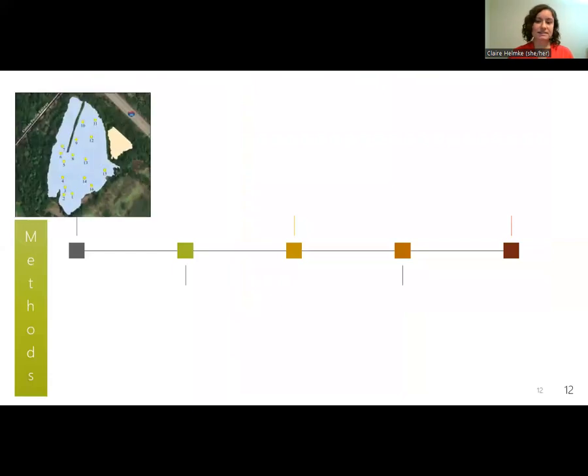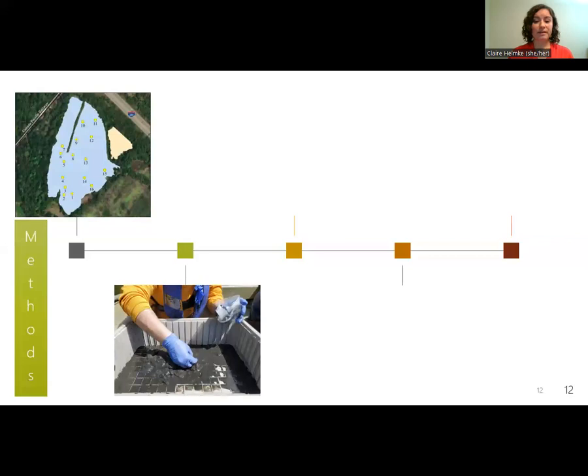We collected 16 sediment samples across Carp Lake in May of 2021 with a Ponar dredge from a John boat. The 16 samples were randomly placed based on how shallow the lake got and how much the wind pushed the boat around. So our sampling location is the exact location samples were collected, which we recorded with a Trimble GeoExplorer with post-processing to an accuracy of less than 100 centimeters. Each sample was drained of water before being emptied into the gray tub, which we washed between each sample. We homogenized the sediment sample, or sludge, removed any vegetation, and stored each sample in a labeled Whirlpak.